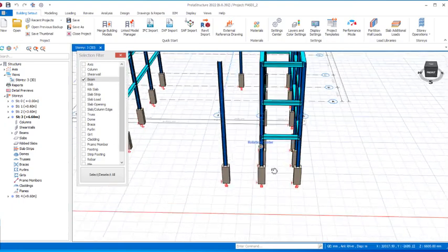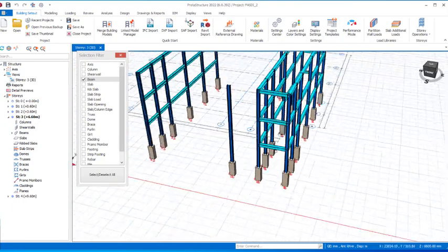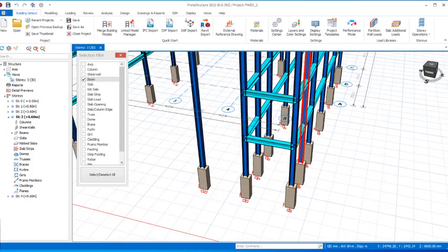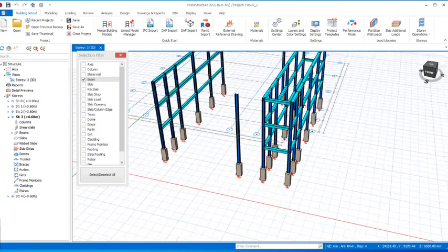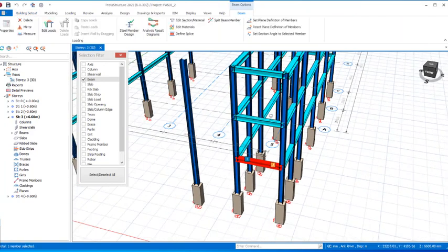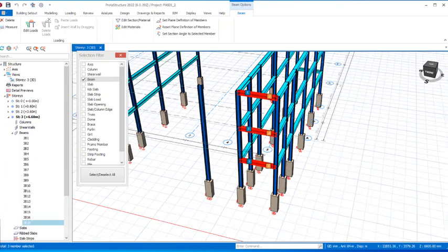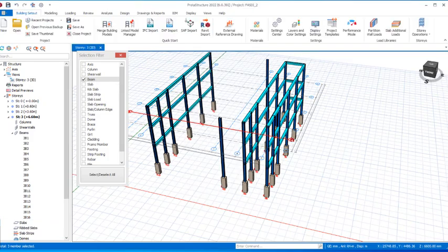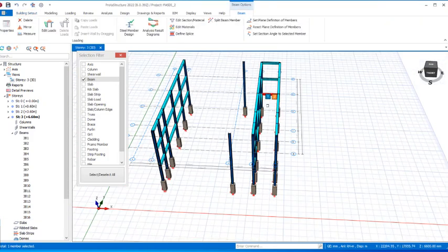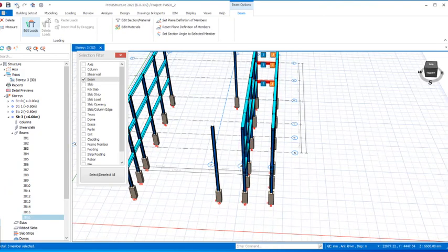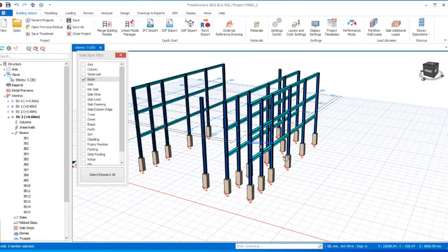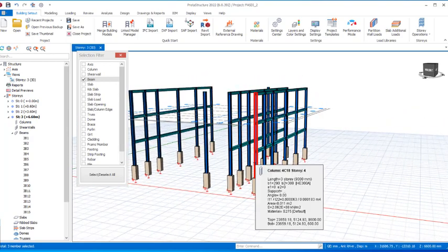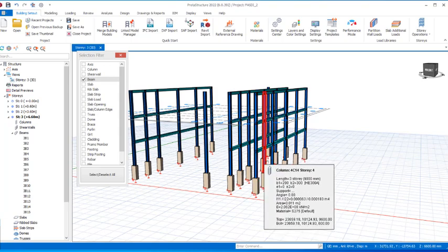Okay, so having done this, now the next thing we want to be doing is the trusses. But we do have an arc here, so we are not supposed to have these stanchions here, okay, because we have an arc here. So I will get this selected, select this, okay, and then I will be able to get that deleted. Okay, options. All right, select this, select this, select this, you have to delete that, and as well these stanchions and these beams will be removed from here. Okay, so select these stanchions, later we will insert them successfully.